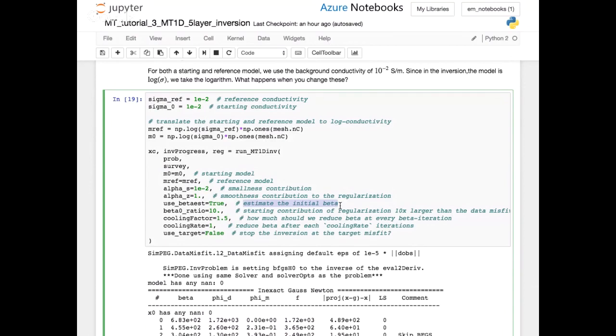What I would try to do in that case is come up with a simplified 3D model in a smaller domain that you can work with. Pick something representative that's complex enough that you can get a feel for how the inversions behave. These are great because they really do run in real time. There are a couple of other linear inversion examples that we have that run in real time. You can get a handle on what your small numbers are.